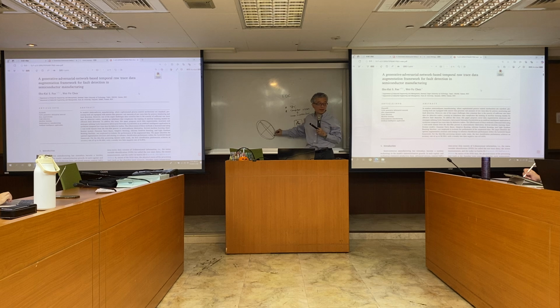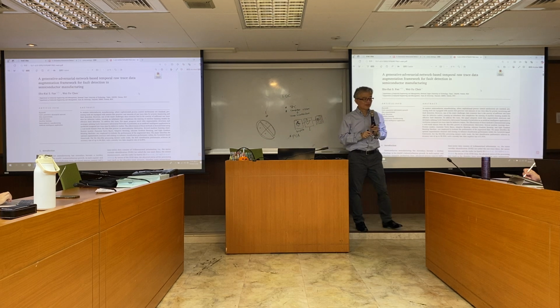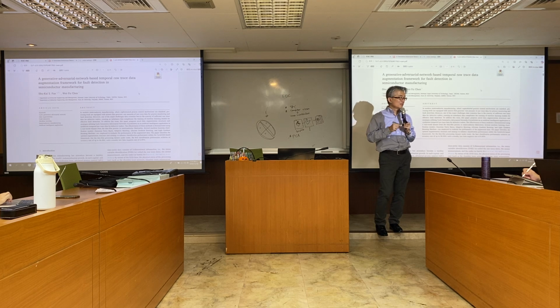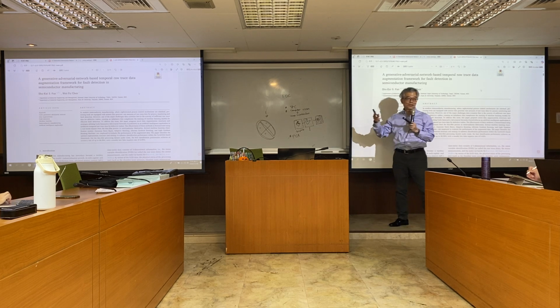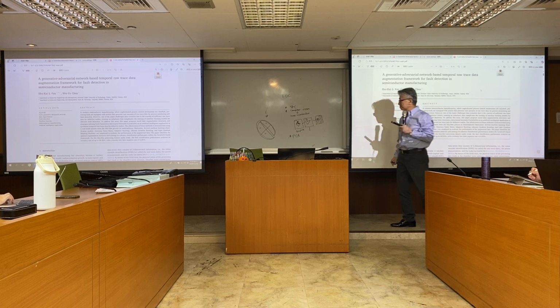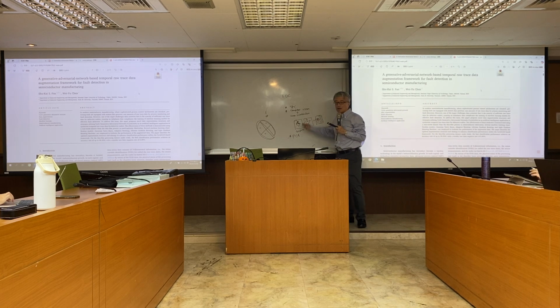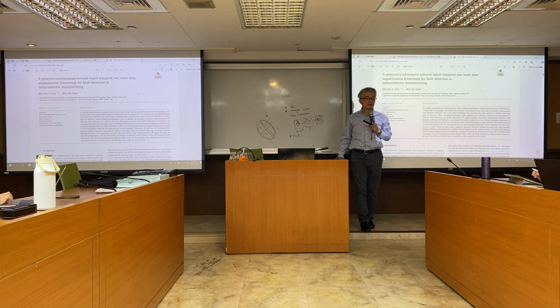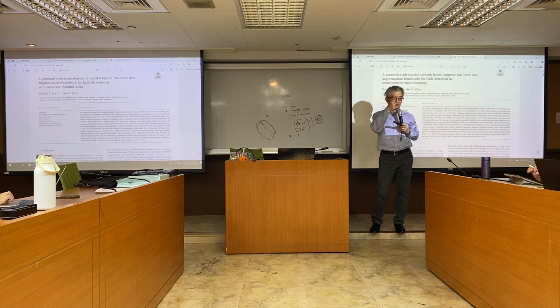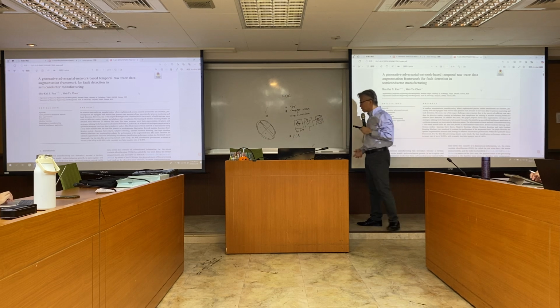Construct the confidence band, so that any point after the PCA transformation is plotted within the envelope. If it falls outside, then a signal is released. This is called PCA. It could be two-dimensional, could be higher dimensional. This is frequently implemented in practice in order to identify the abnormal condition.